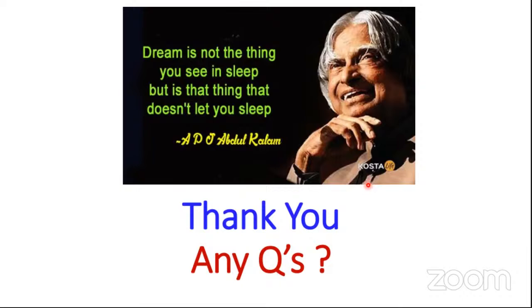porosities will be there. For example, when we are using very high laser power, not only melting happens, in addition to melting, the metal starts to evaporate, and if it is an evaporation process, then there is loss of material that can be associated with porosity. So optimizing the parameters is one of the very key important steps in the metal additive process.